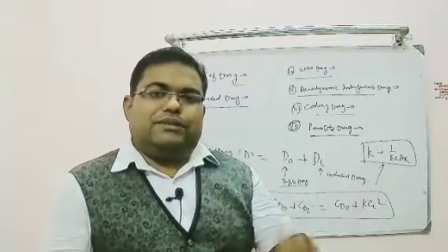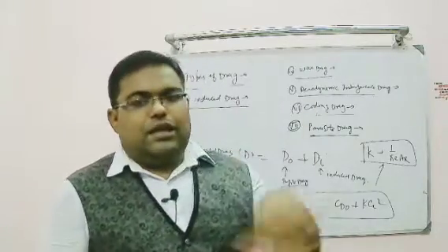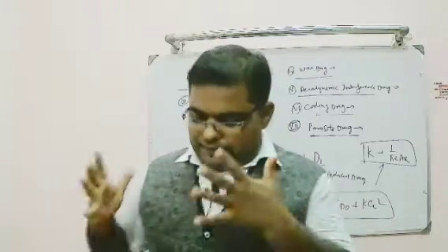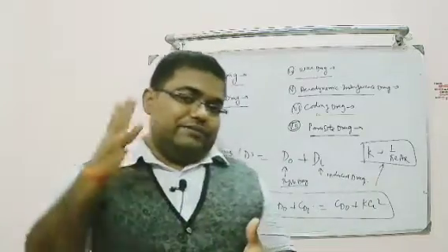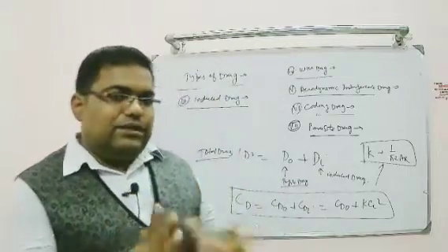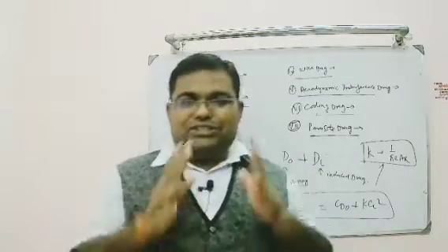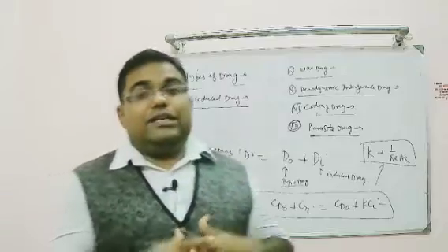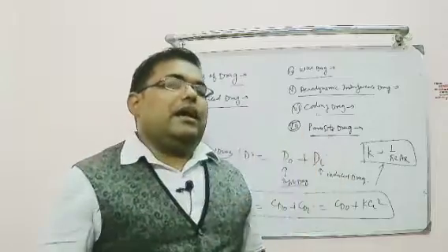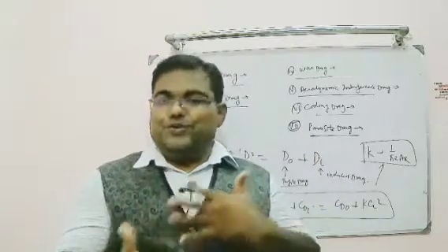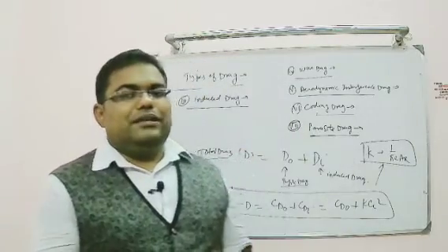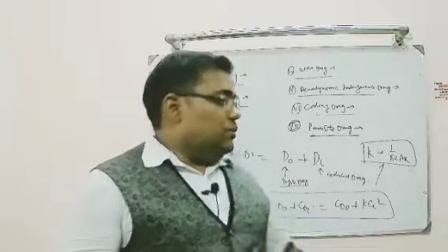Today we have discussed the pressure distribution. We have seen how important pressure distribution is to find out the aerodynamic forces, and we have developed a relationship for lift and drag, and seen examples of lift and drag over different kinds of geometries, right? Finally we came to the conclusion that streamlining of objects is very necessary for vehicles which travel through the air. That's why all the parts of the aircraft exposed to the outer atmosphere are usually curved. We don't want any sharp corners, because a sharp corner will contribute a large amount of drag. That is called streamlining.